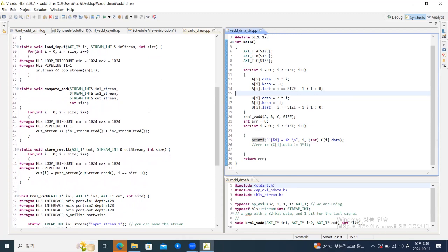And there is a compute unit, which is basically an adder. And then you have another FIFO, and you have another DMA. We often call this kind of architecture a decoupled load and store, meaning that this compute unit doesn't care about data read or write, but only when there's data ready in the FIFO, it just pops one and pushes here.